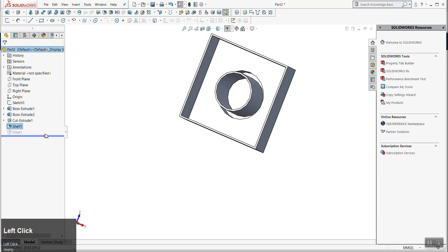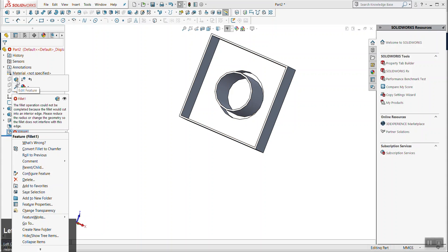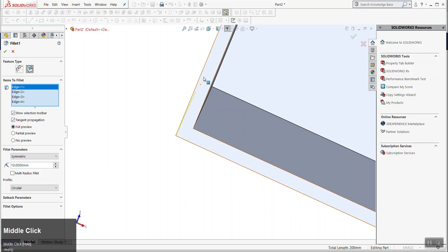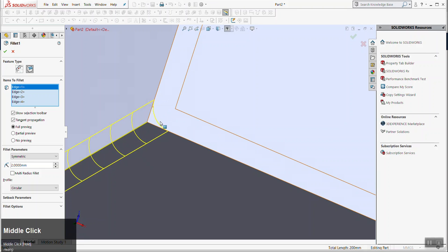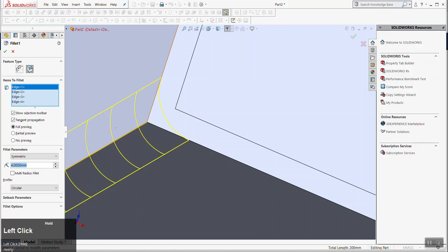But now if I roll down to this fillet, it gives me an error, okay? This is what I'm talking about, in the tree, the order of operations is important. The reason why it's giving me an error is because the fillet, the curvature that I'm trying to put on this corner, is going to eat into the inside of this wall, right? So if I drop this down to 2, it gives me this wireframe. It says, hey, you can do that. As I slowly click up through increments, 3 lets me do that. 4 lets me do that. Let's see, it probably will let me get to like 7.